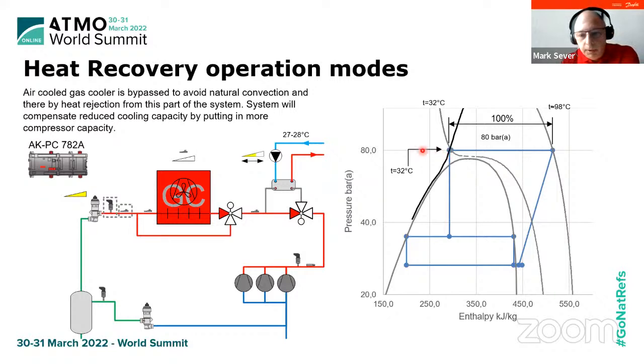So when we are moving this line here to this optimum COP point, we are decreasing efficiency of the CO2 system. Your compressors will start to work more, so we will have a much higher mass flow through this plate heat exchanger here. At the end, we will be able to recover the full heat from your CO2 system.